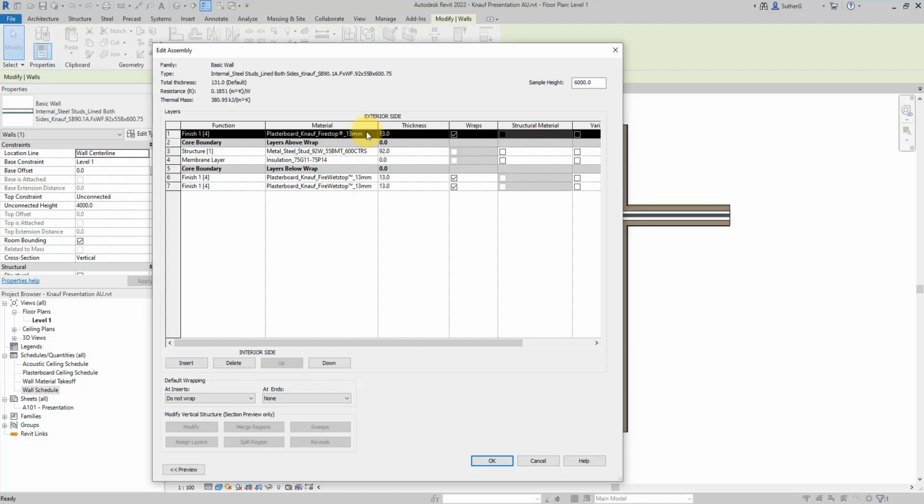The second thing we see is how the framing material is named. Although we won't see the cross-section of the studs in our plan views, we'll still know the specific stud arrangement needed to achieve our desired wall heights, since it's instantly documented in both the family parameters and the materials themselves. The third thing we see is that insulation is included as its own material and given a specific name. Again, this setup will help in the material takeoff later.